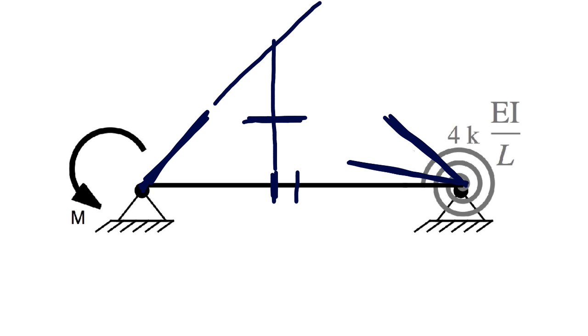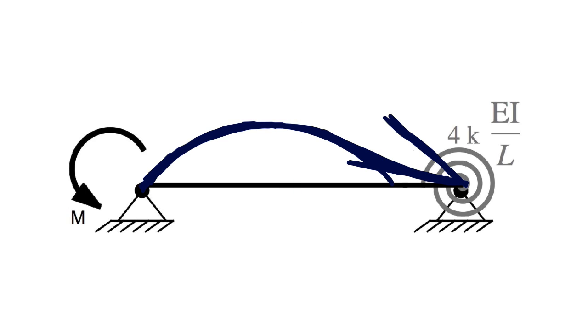Next, we draw a rough arc curving downwards and starts tangent to the stub at the left end. We try to have the maximum height tangent to our horizontal guide at about 40% of the length of the beam from the left end. For the right end, we draw a parabola that is tangent to the stub and tangent to the arc on the left so that we get a smooth transition. Next, we smoothly join the two curves, smooth things out, and remove extraneous lines.